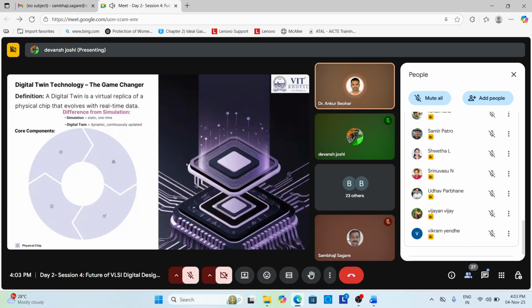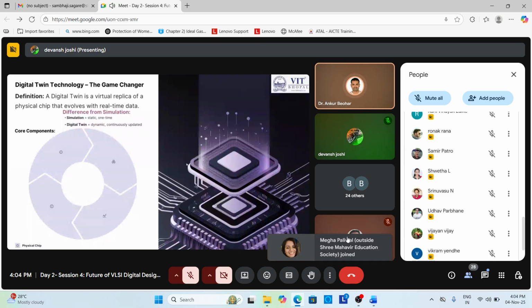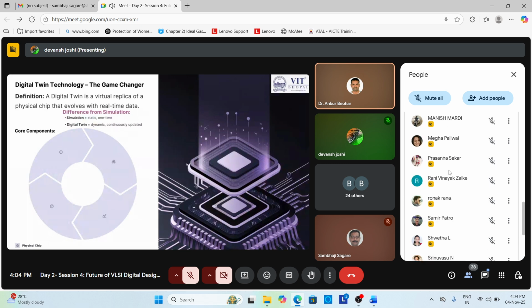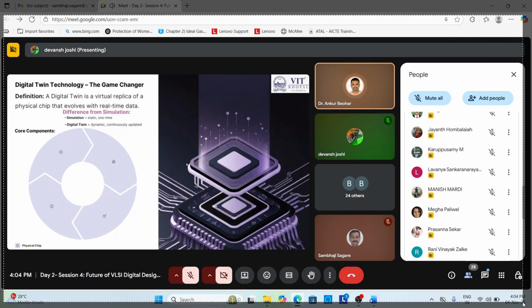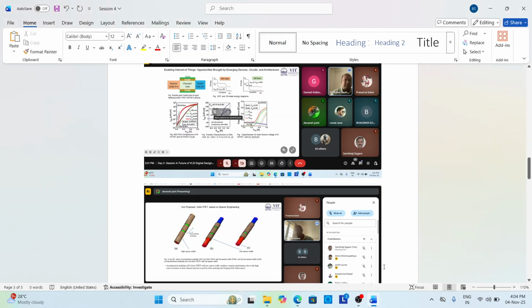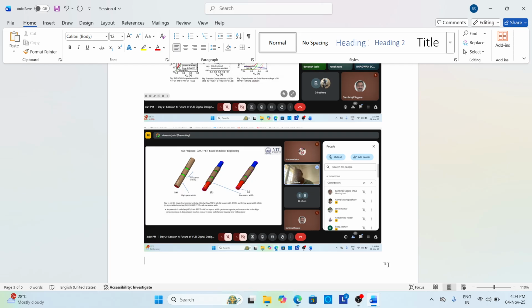where it would be the starting point to implement right now, where we can have the chip performance, functionality, power, and area requirements. According to this, power and area both are very important terms here, where we can go with the testing and specification. When we get the specification requirement for the processor and the frequency as well, then we'll go for the architectural design, where we have to take the decision how the functionality will be implemented at a high level, choose the number of ALUs and the memory hierarchy, like pipeline stages, etc. That we will go under this.